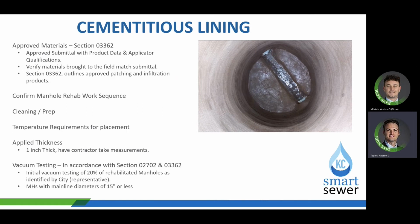Cleaning and prep. So this is an important one. Try to get your eyes on the cleaning before the contractor begins cementitious lining. Make sure that they've got the manholes power washed. There's no evidence of loose debris or anything still within the manhole. There's no oil or grease spots. The manhole steps have been removed, and also that they've sealed any potential active leaks, as well as temperature requirements.